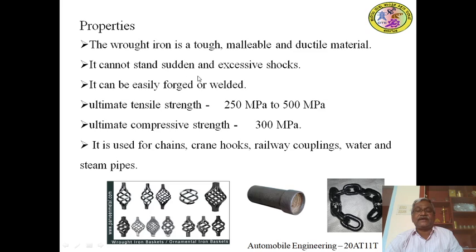It cannot stand sudden and excessive shocks. It can be easily forged or welded. Its ultimate tensile strength is 250 megapascals to 500 megapascals. Ultimate compressive strength is 300 megapascals. It is used for chains, crane hooks, railway couplings, water and steam pipes.